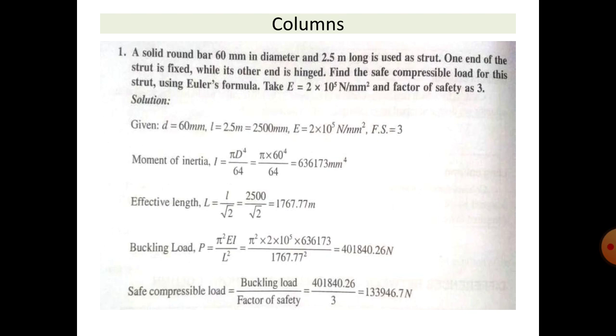To calculate that, you divide the maximum load by the factor of safety, which is given as 3. First convert your meter dimension units into mm.